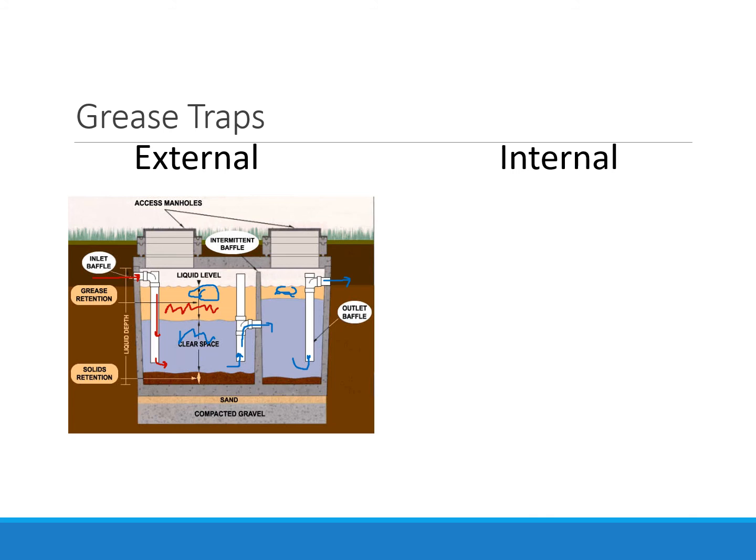And so from the top, from outside in the parking lot or wherever you have your grease trap, you have a manhole or a lid, these things right here, that can be opened so that this fat can be vacuumed out. And trust me, pay somebody to do it, because there's nothing in the world that smells worse. That's the voice of experience. Just pay somebody to do it. It's money well spent.